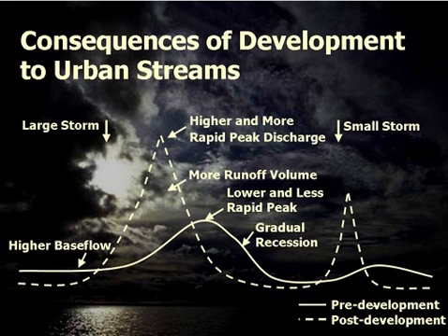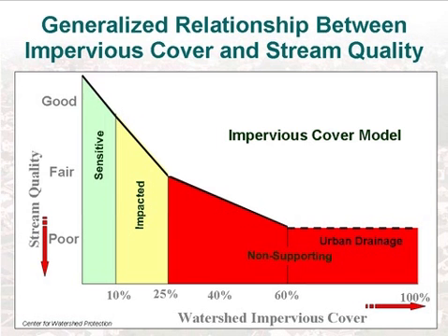Yeah. And again, this is a generalization. The Center for Watershed Protection has done research in hundreds of watersheds on the East Coast and in the Midwest areas. And certainly there's going to be a lot of variability. And I know John feels like there are some different conditions out west, right, John? Just a quick comment. In arid and semi-arid areas, we actually commonly see base flows increase as a consequence of urbanization in many streams. Just a quick note. Oh, sure, yeah.